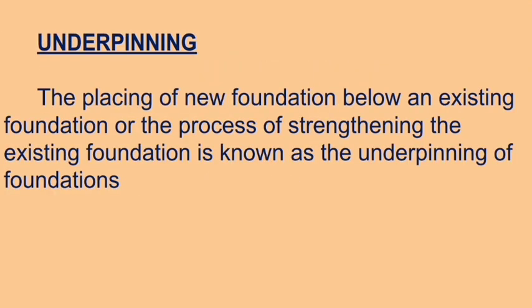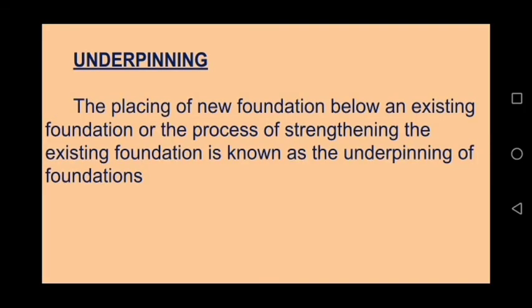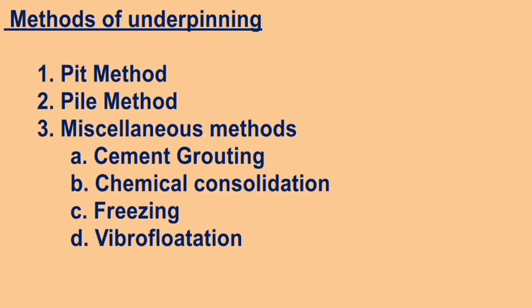Now the term underpinning. What is underpinning? The placing of new foundation below an existing foundation or the process of strengthening the existing foundation is known as the underpinning of foundations. Methods of underpinning. First one, pit method. Second one, pile method. And third, miscellaneous methods.